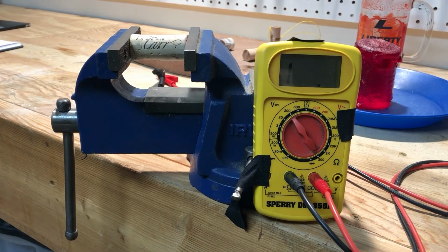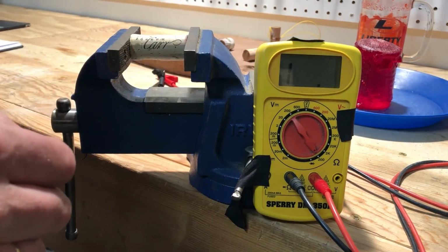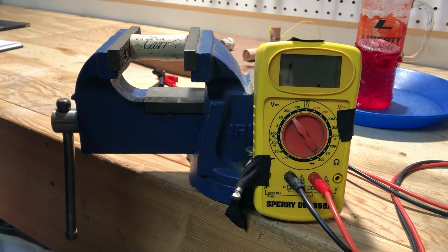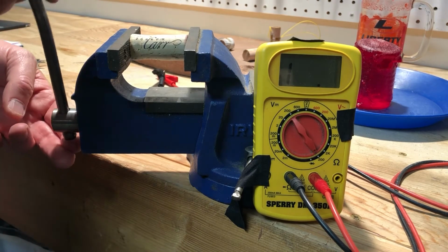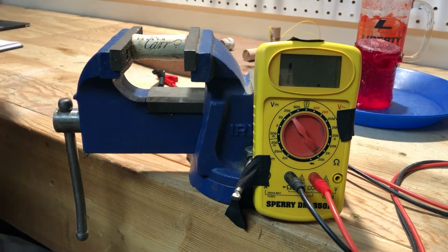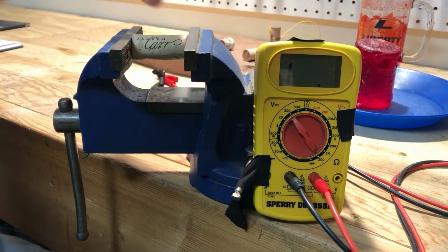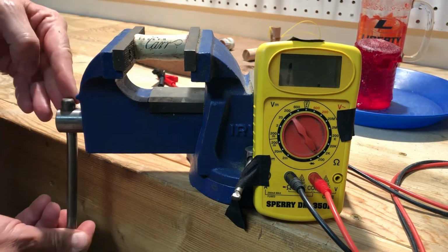We can also put a sample under stress in a vise. In this vise, we can apply about 1,000 pounds of force on a sample. I can measure the sample's shortening and bulging with a caliper. For example, in cork, we can measure the shortening of the sample, but we see almost no measurable bulging in the horizontal directions.